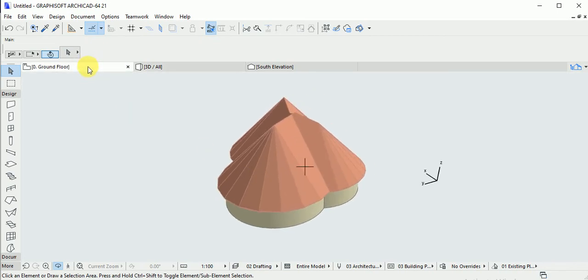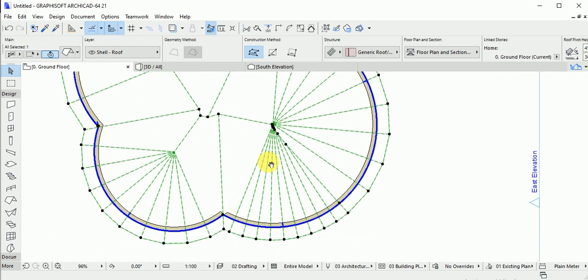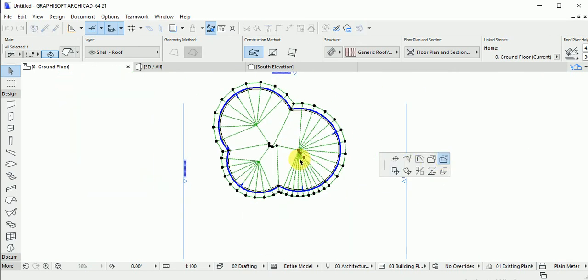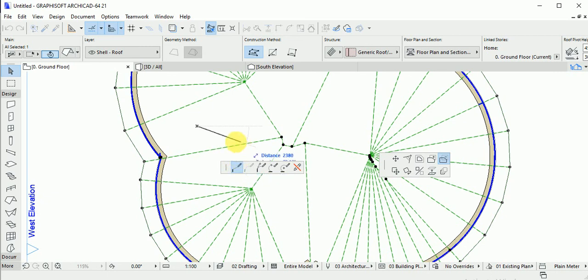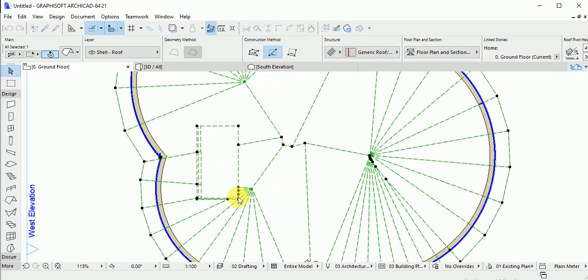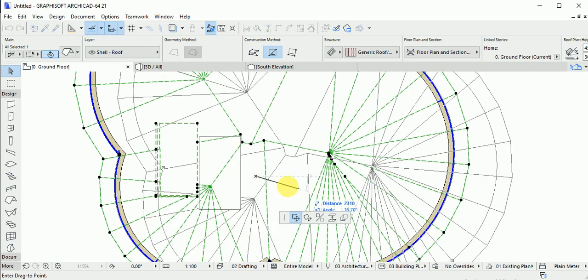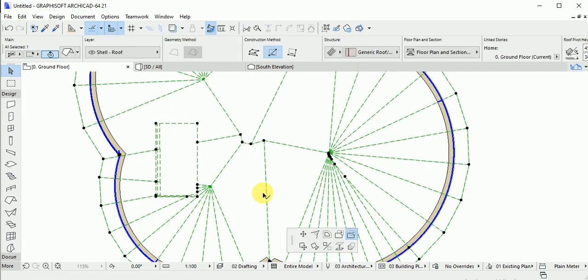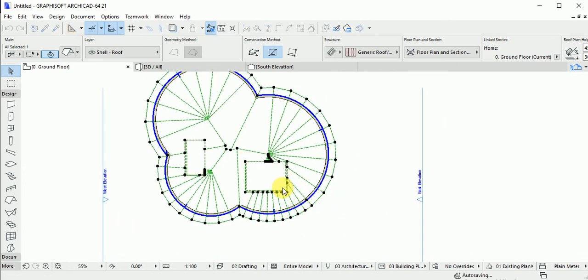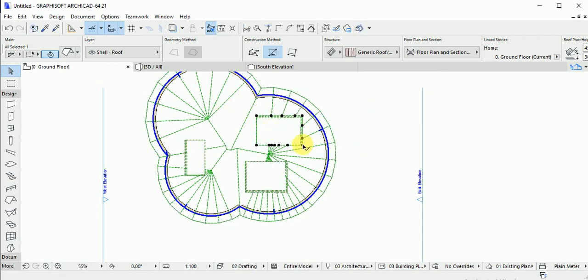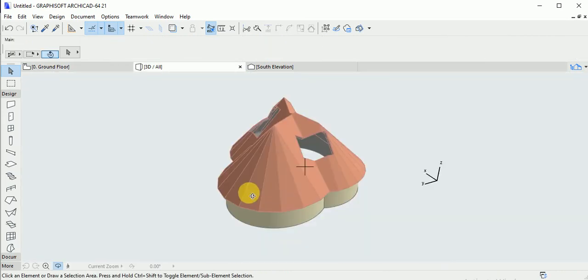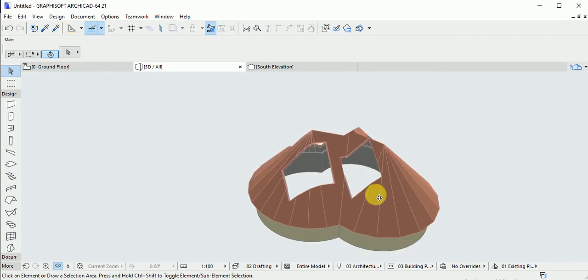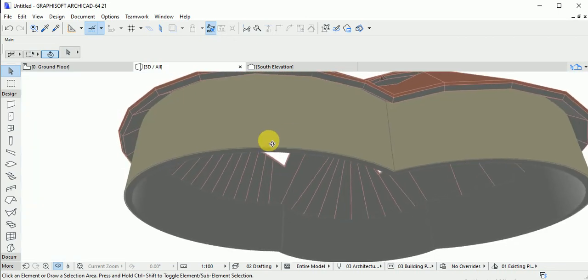So still, you can perforate it if you want to. So you click on this, click your minus sign, then you make a hole on it. Make plenty of holes. Click on it. Because it's on minus sign, I'll make a hole. Click on that. Make a hole. So what we are having now, once you go back to your roof, you will see spaces on them. Why? Because you chose to make a hole on it.